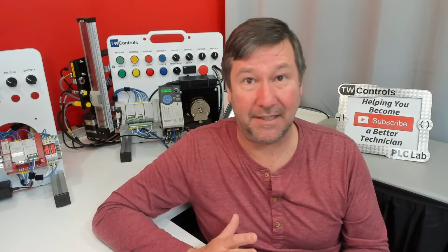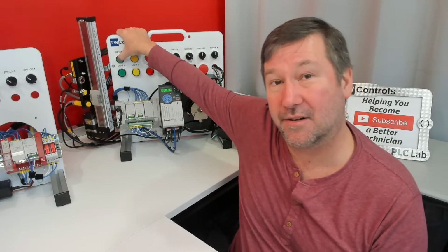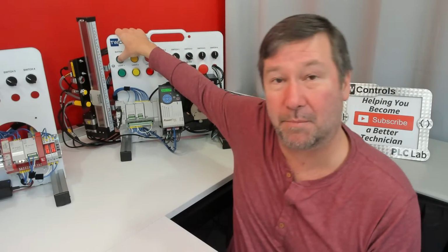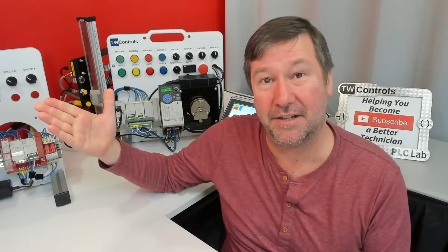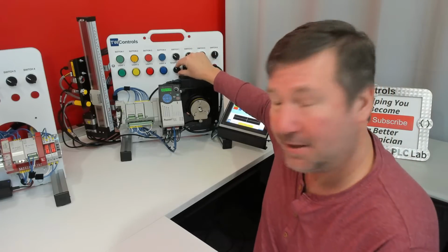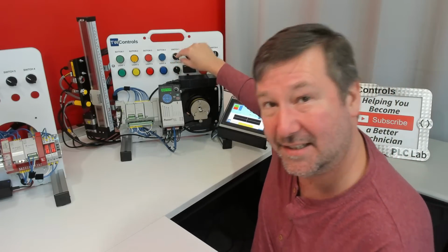What's the difference between a digital and analog input? So digital is what makes up all the on-off bang-bangs of the world. So I press this button here. It's either a 0 when it's not pressed, or we press it and it's a 1. That's the only two values it can be. That is digital. Here we have a potentiometer, and we can turn it to different locations. This is analog because it's going to be in a range between two points.